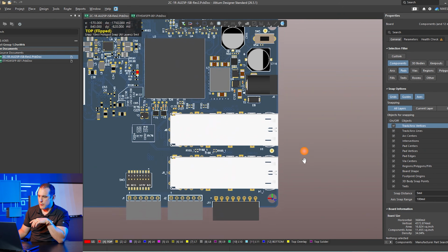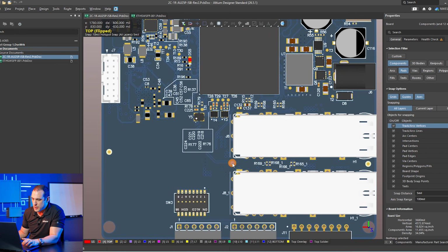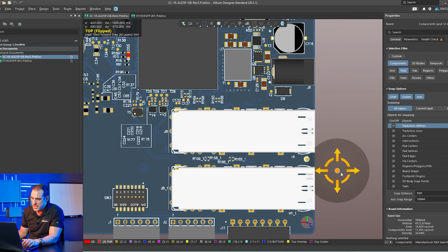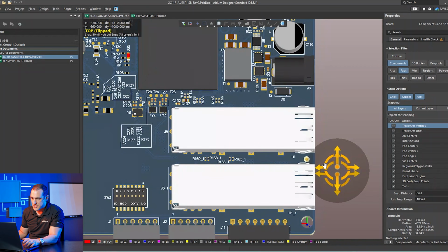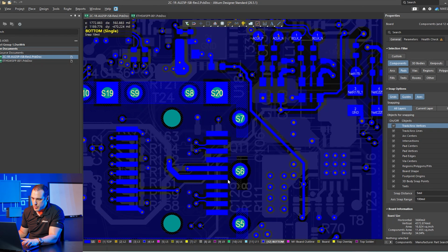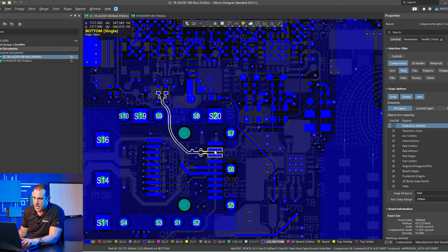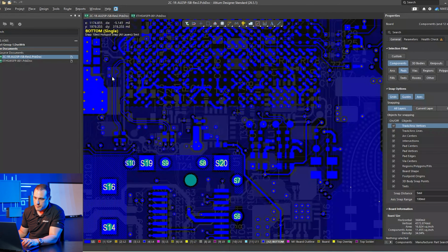Now the first project that we'll look at is an FPGA board which has two 10G interfaces, which you can see right here. Now I've shown some variations of this design in other videos, but we're going to look at this much more compact version here in this video. So here you can see the design in 3D with our two SFP cages. Now here, if I go into 2D, you can see here we have two SFP connectors, and then here on the highlight you can see where those lines are being routed all the way over here to the FPGA. So the routes are pretty short in this design.